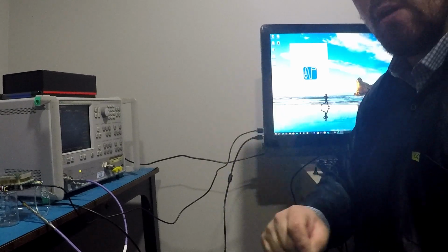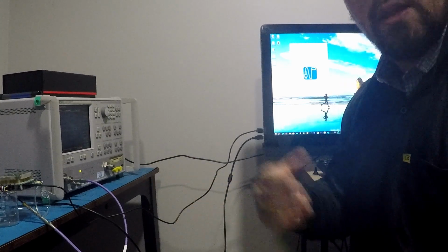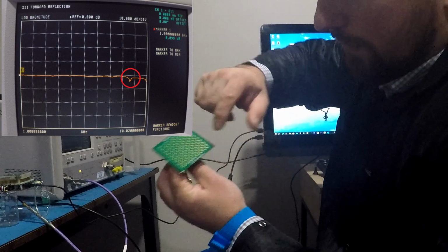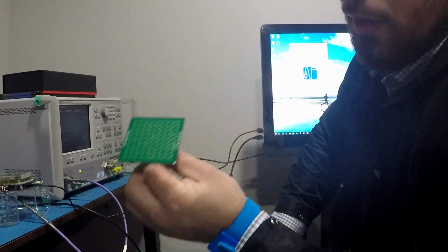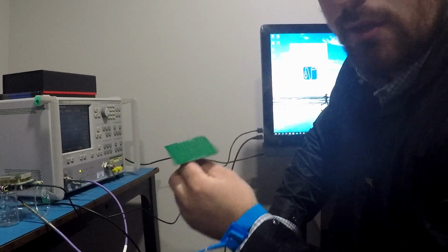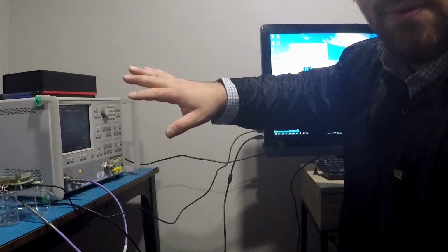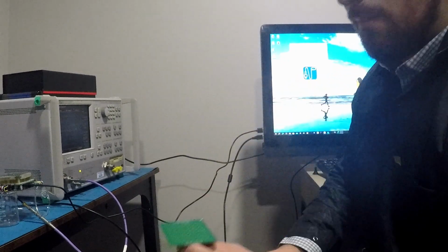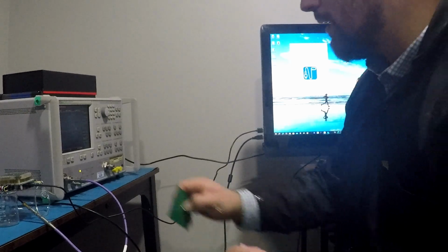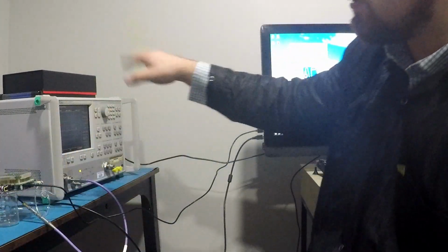There's also going to be a feature about 9.4 gigahertz you'll see above the antenna. Even if it's not on, it's there. It comes from the center patch of the pixel. That's how I verified. I took one of the boards and just didn't put any passives on it, just measured return loss, and it was roughly there, almost same magnitude. Obviously with some of the passive components for the switch, it did get a little bit loaded, but we saw the same phenomenon from this. It's that resonance up there by 9.4 gigahertz. You'll see it in the subsequent tests we do.